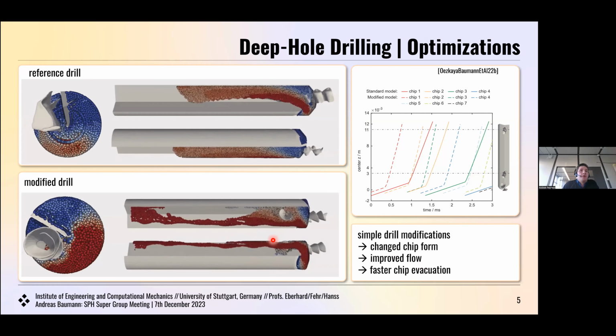So our idea was, okay, let's add a second fluid outlet behind the cutting edge, which allows the fluid to divert around the cutting edge, thereby cooling the cutting edge more efficiently, and then getting out of the borehole through a second fluid path. We did some tests with different designs. So we have the reference up here. We also see in the streamlines that we have not much flow behind the cutting edge. We added a slight second fluid outlet on the right-hand side.